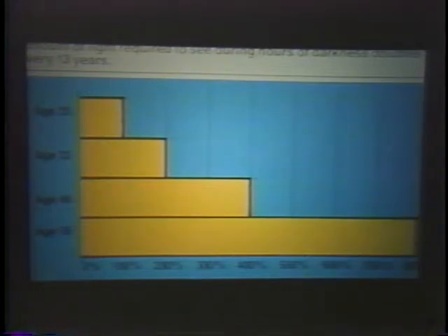The light required for sign detection and legibility increases geometrically with the age of the viewer. Here is an example of a reflectivity test. Notice the stop sign at the right in daytime. This is the same location at night. The sign that you see is not the original sign, but a test panel that was placed below the permanent stop sign. The permanent sign has lost all of its reflectivity and is completely invisible at night.